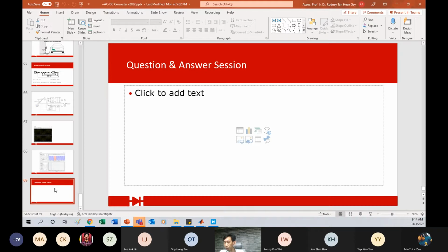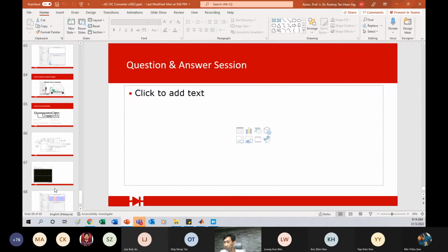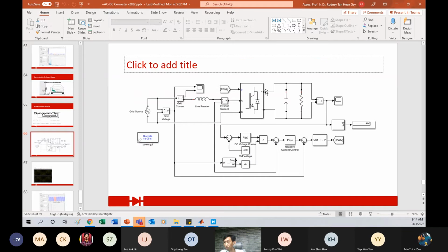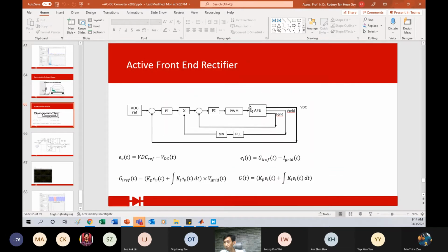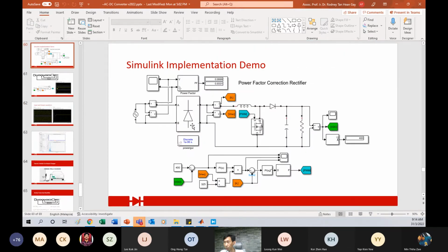We also talked about the switching devices: diode, MOSFET, IGBT, thyristor. These are the 4 types commonly used in converters. You will notice that for DC-DC converters, mostly they are MOSFET. For AC-AC or AC-DC, mostly thyristor. Of course, even for this AC-DC, we still use MOSFET. And in the PFC also, we have diode and MOSFET for the switching.